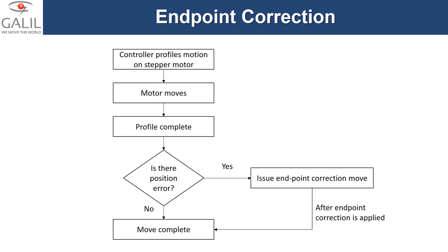That's where using a mode like endpoint correction can be beneficial. Let's go over how the mode works. The controller profiles motion for the stepper motor. The motor then moves based on the commanded steps from the controller. The controller will complete the profile.